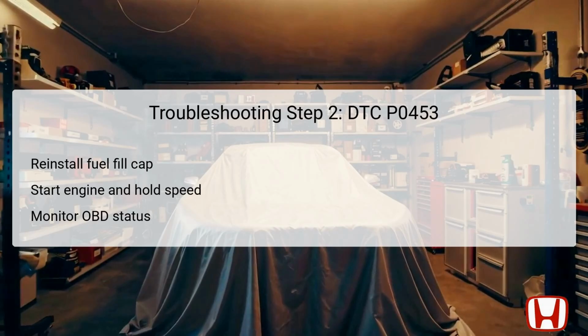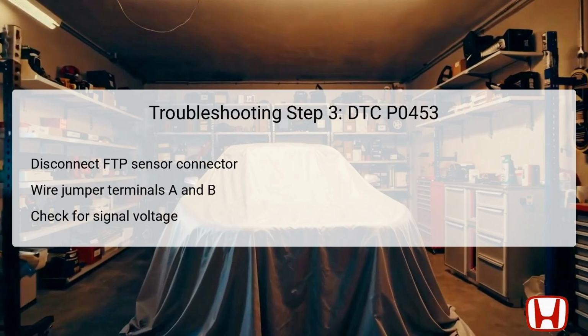After idling, monitor the onboard diagnostics (OBD) status for DTC P0453 using the HDS. If the HDS indicates failed, it confirms a recurring fault, supporting the need for further investigation. Conversely, a past condition suggests no current faults, indicating an intermittent issue, signaling that connections or terminals might need inspection.